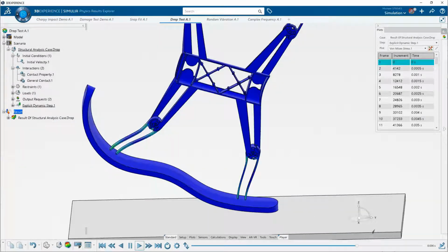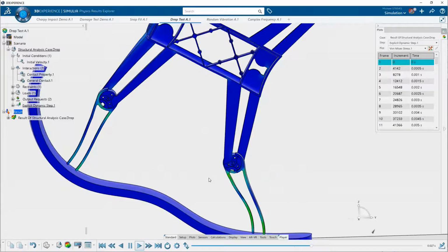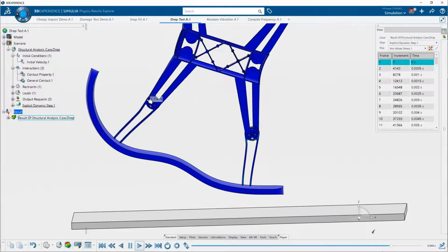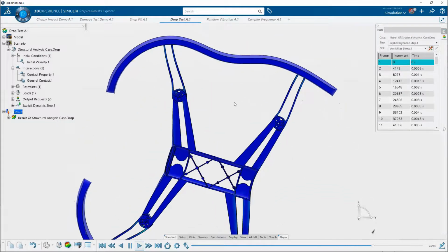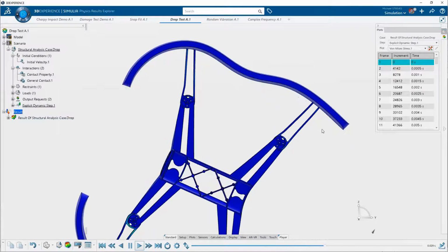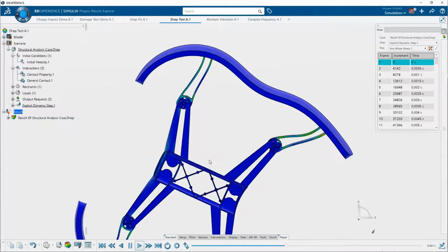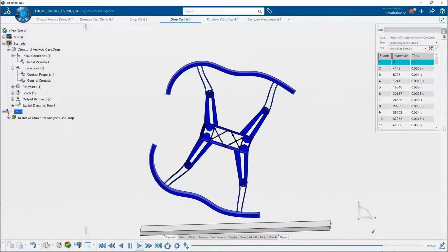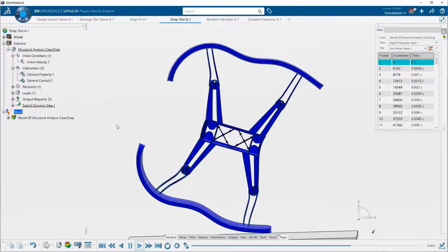So, during this impact, you may be thinking that the highest area of stress may be in that bottom area, or are some of these clips going to disassemble? Well, we can answer these questions and, again, predict the product performance here virtually, identifying the higher stress in the actual opposite bumper of this assembly. I'll let you just enjoy this animation for a second before I move on.